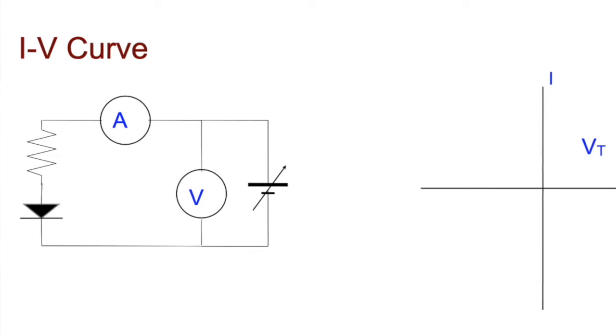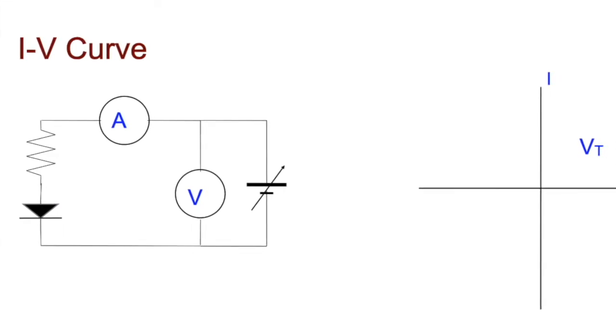We can build it into a circuit, replace the resistor with now a resistor and a diode in series. And there's some subtlety as to why the resistor has to hang out there. It's actually to protect the diode from burning up. So it limits the amount of current that this thing will actually allow to pass through, because we know, like a valve, a diode allows current to pass in one direction but not in the other. And so we can already imagine what kind of shape a curve like this would have.